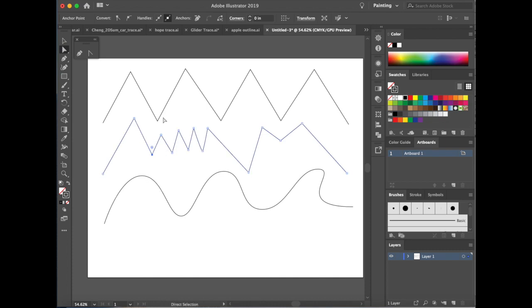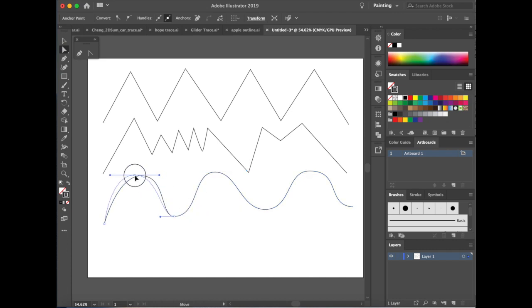So an angle point is just the point. This is a Bezier controller. You can drag that to create a curve. So this side of the control handle controls the curve before the point. This side of the control handle controls the curve after the point. And so together I can change the angle and I can change the distance of the handle from the point. I can go back and make my waves more regular if I would like, and sometimes you have to adjust the point before or after to be able to get the right curve that you are looking for.